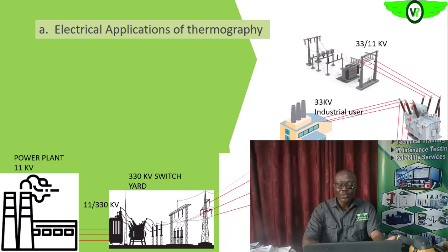So when you have, let me say, something like a loose connection or a connection that is not properly made, you see that the current, as it's flowing through at that loose connection point, will meet a higher resistance at that point than what is normal. Are you getting it?